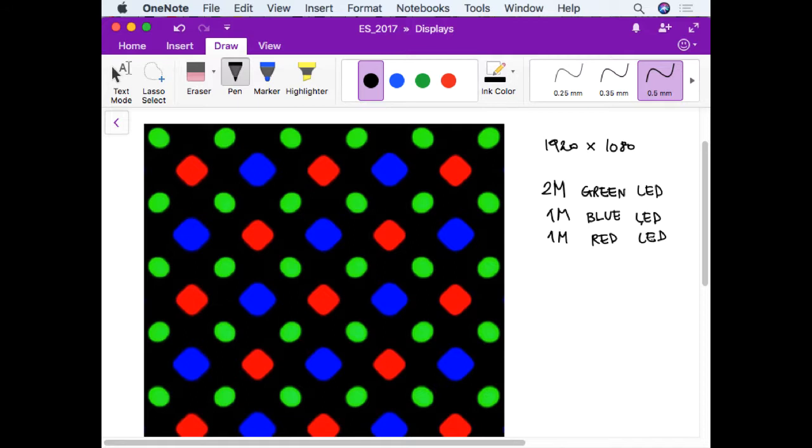Okay, for each of these 4 million LEDs, of course, you need a specific addressing circuit and TFT plus capacitor, plus in practice you have a few more transistors to keep the voltage on the LED constant until refresh. So you have a few tens of millions of transistors for a typical full HD display, all with TFT technology.